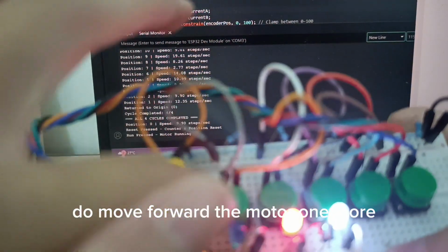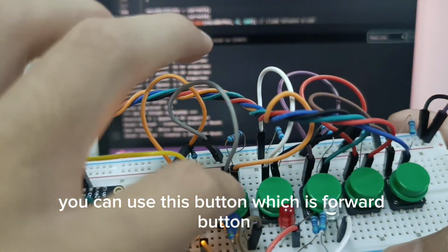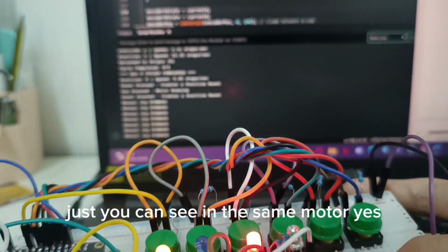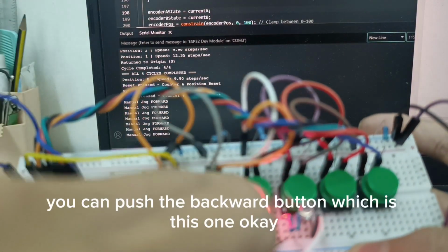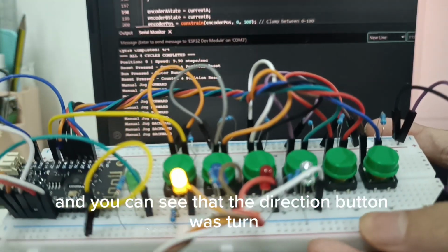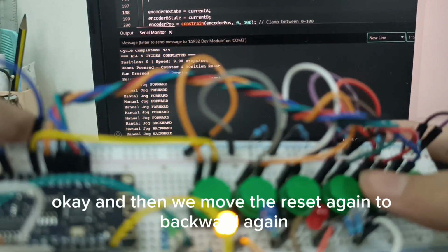Or, let's say you reset and want to manually move the motor, you can use this forward button. You see the direction LED is on because the motor is going forward. As you can see in the serial monitor, the motor jog forward. If you want to go backward, you can push the backward button, which is this one. You can see that the direction LED turned off, and the serial monitor says manual jog backward. Then we press reset again